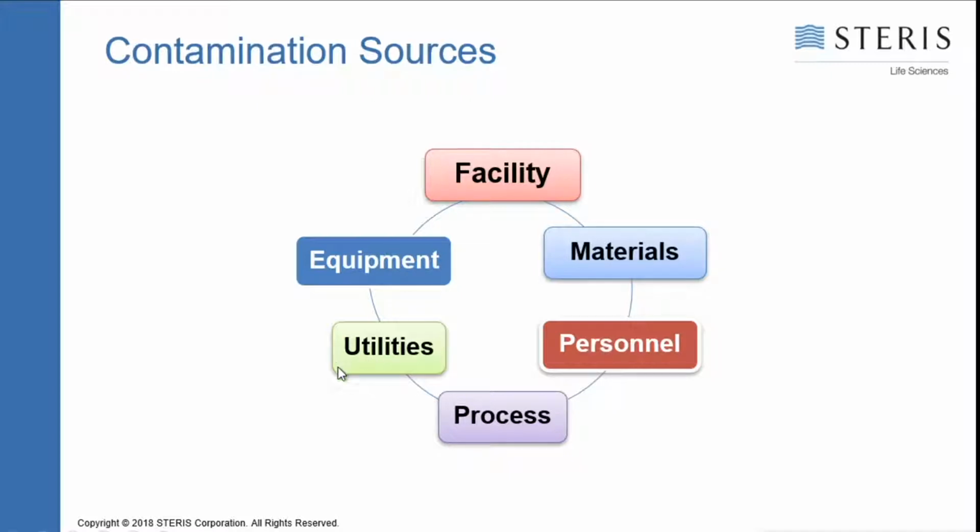And then from a utilities standpoint, we talk about things such as the water sources in the clean room. We also will talk about compressed gases that you're using. Those are all also potential sources of the contamination. Then equipment in the room would be another key thing, and where you place the equipment as well, because you don't want to block any of the entry or exit vents in the room that would affect the HEPA filtered air in the clean room.